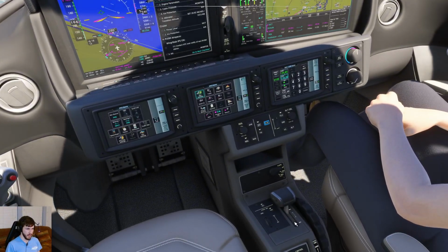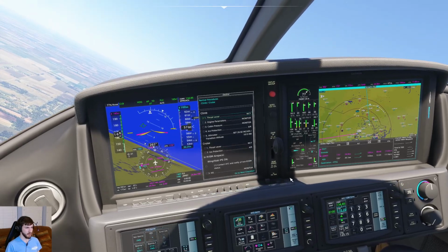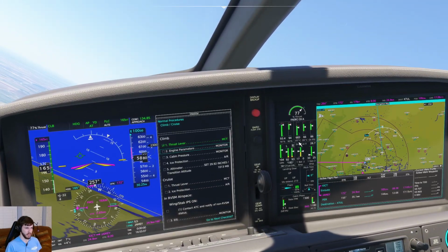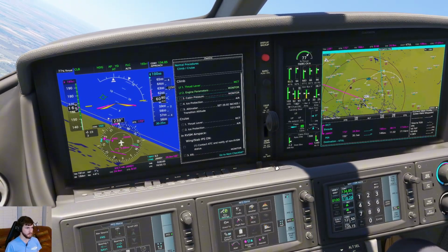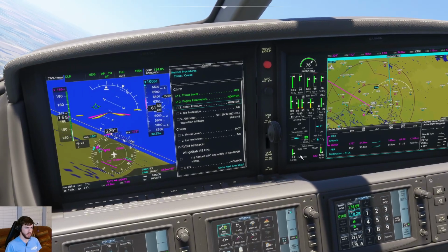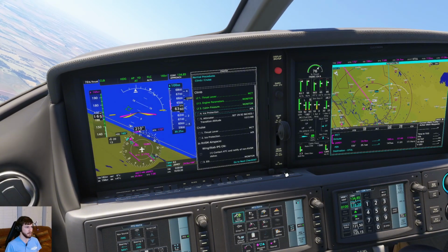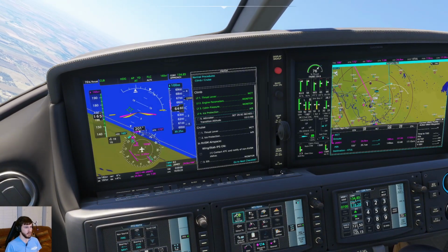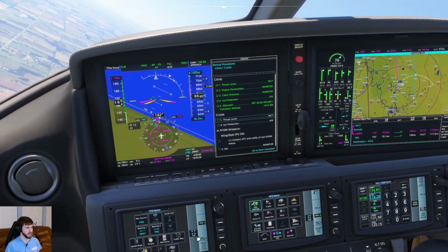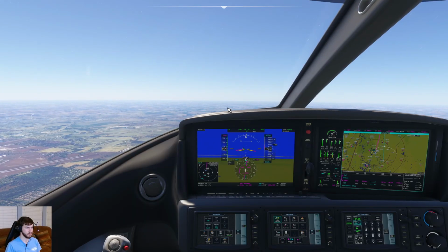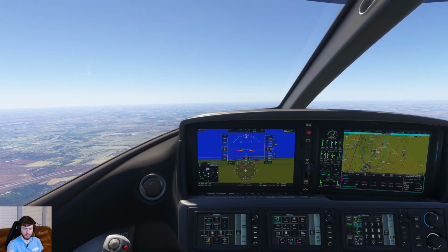Climb checklist. Thrust lever is in MCT, that's maximum continuous thrust. Good. Engine parameters monitor. Looks like everything's in the green and stable. Electric stuff looks good as well. Cabin pressure, looks like we are pressurizing and the cabin is climbing. Ice protection as required, it's all off, we don't need it. Altimeter, we're not going to go through the transition altitude today, so we won't worry about that. Climb checklist is complete.